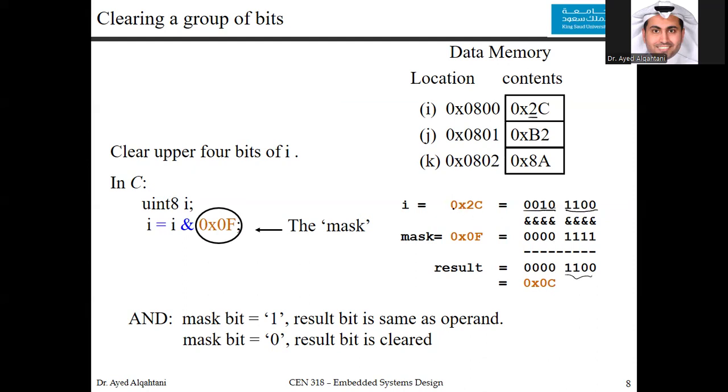The result of ANDing the hexadecimal value 0xC2 with the mask 0xF0 is going to be C0. Notice that we kept the C, but we zeroed out the 2. So now we know that the appropriate mask is supposed to be 0xF0, which is this one in binary.